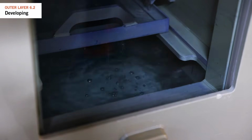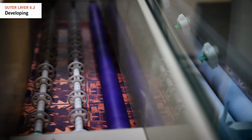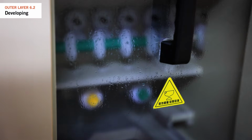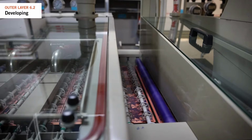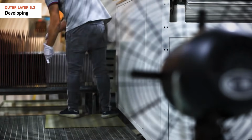The key challenges with the process are controlling the chemistry and the processing of the panel through the developer, so we only remove what we wish to remove. This is one thing we check during our audits. Also, we check the developers to make sure we rinse right after developing to remove the unwanted resist and prevent it from sticking back to the panel.